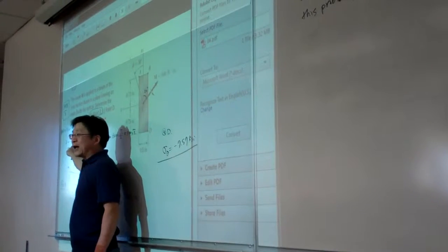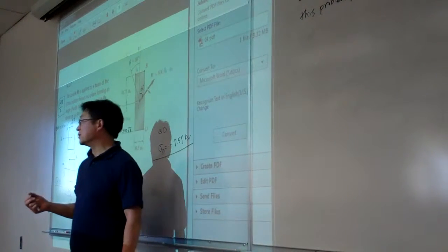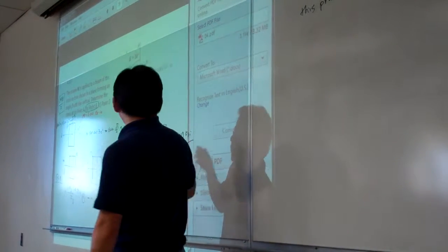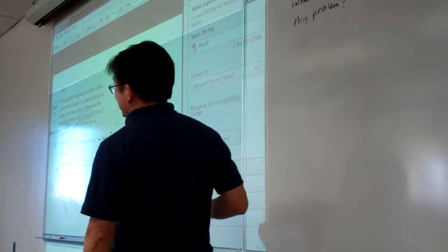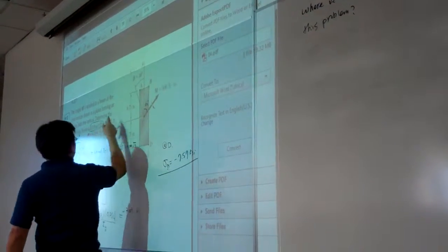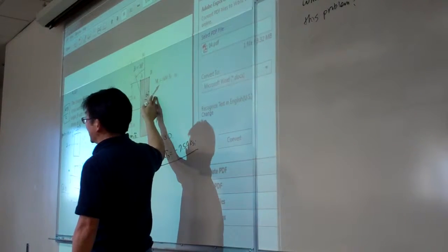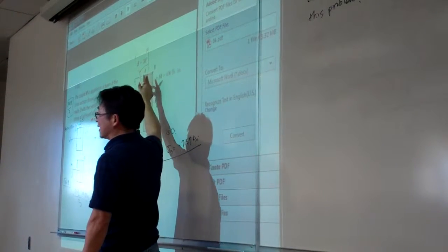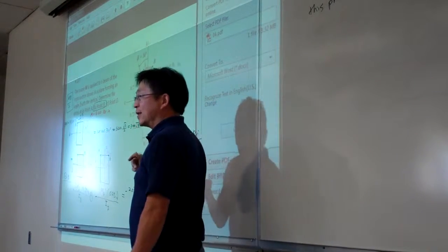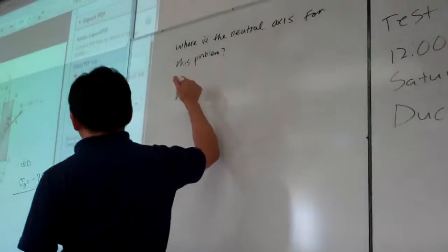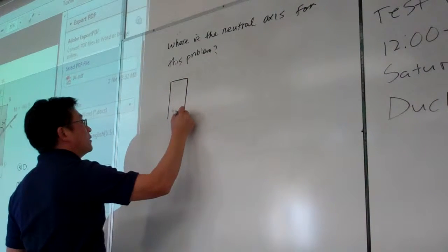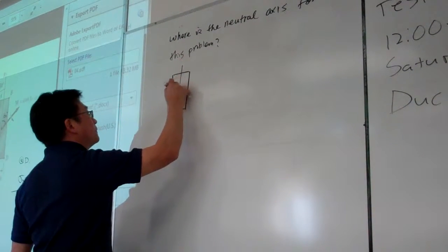And again, the neutral axis is where, by definition, the stress is zero. And the neutral axis always is a straight line on the cross section. Which means you can see here the ABD, here you can do the combination. So as long as you can figure out some points, then you can use geometry to make a straight line. And that could be one way. Otherwise, we can try this way. Let me redraw this one again.